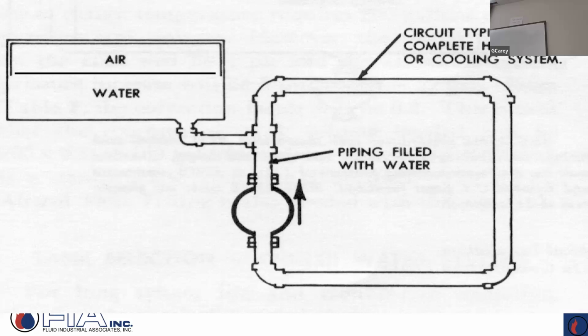And that's the paper he wrote to the industry saying it's very important where you put this pump relative to where this tank connects. Because if I'm pumping at, again, back to that point of no pressure change, if I'm pumping at this connection, I can't change the pressure in the tank because I can't change the volume of water, which means I can't change the volume of air.